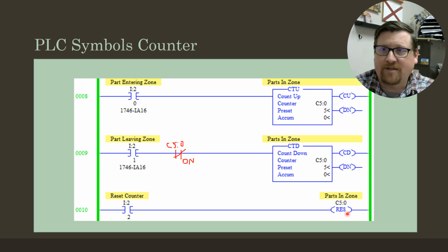On the last page, we talked about a retentive timer: when you activate it with the switch, the timer starts. With the retentive timer, if you take that impulse away, it holds whatever time is in it, so that if it gets a pulse again, it just starts back where it was. Well, if you want to get it back to 0, you have to reset it, and that's what this is.